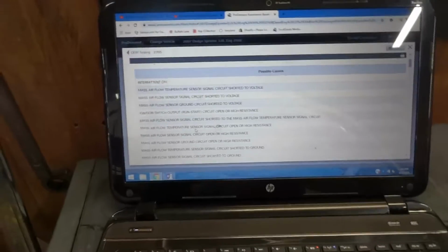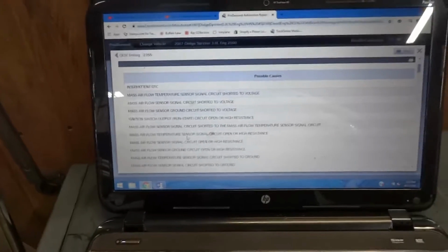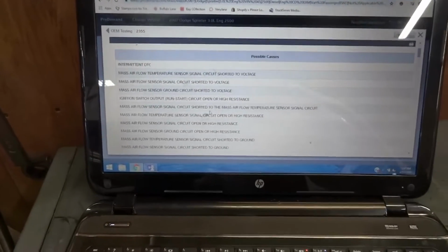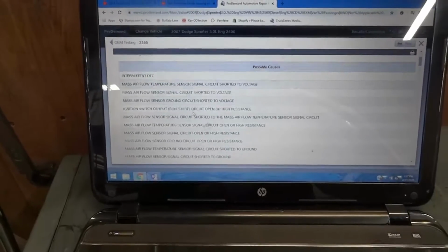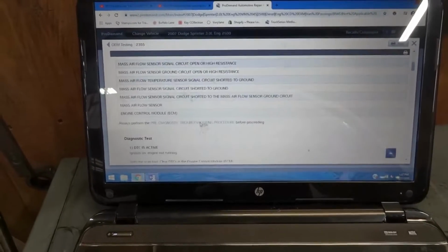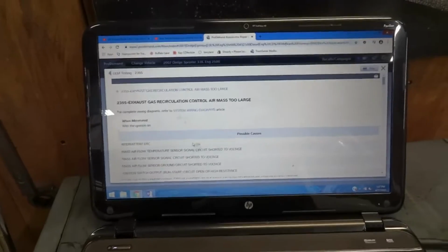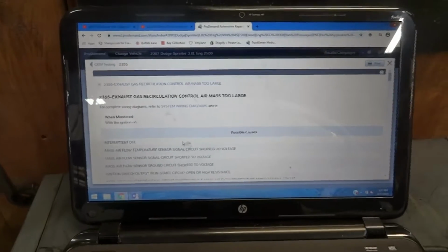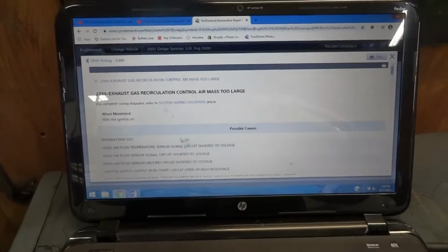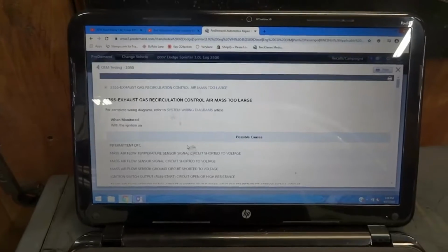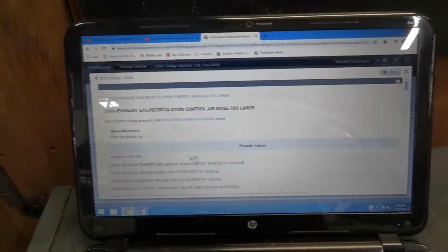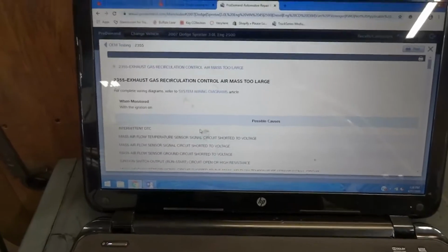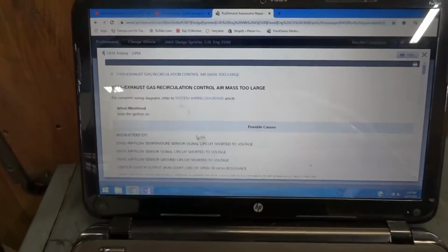So the good thing about this is that it's leading us back to the mass airflow sensor circuit, or the mass airflow sensor maybe being skewed or not operating properly. So now what we need to do, I mean, when we looked at live data, everything seemed pretty fine. But again, that is processed data. The computer is looking at the input from the mass airflow sensor, and if it's completely skewed, the computer can ignore it and just use some default strategies that are inside the computer.